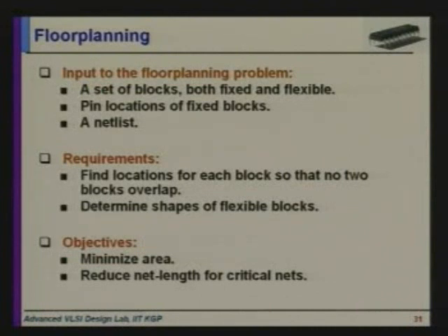I need to place those blocks on the floor area, right? This is the placement problem. The floor planning problem is also a placement problem. It's just terminology. The difference is that I have fixed and flexible blocks as well, right? So placement of fixed and flexible blocks together is a floor planning problem. So the placement problem is a sub problem of the floor planning problem.